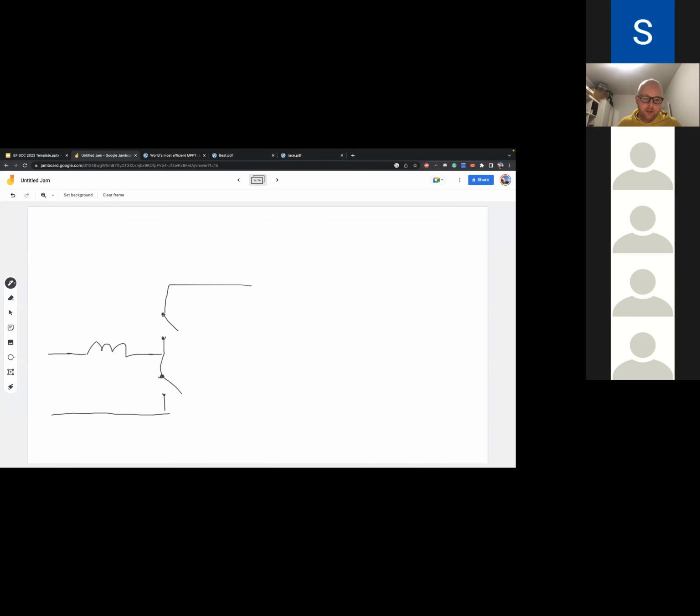And then usually you have some capacitance. There's multiple factors that contribute to switching loss, but let's keep it simple. Let's say there's little capacitors in parallel to the switches on the MPPT. This is the input of the MPPT, where you connect your PV. This is the output. And what happens is every time you turn on a switch, you short this capacitor, and therefore you lose all the energy in the capacitor.